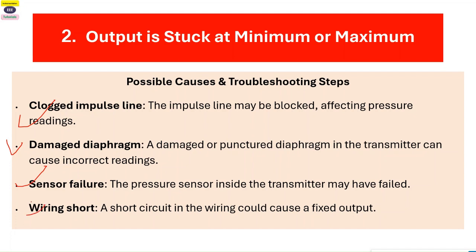So you have to check whether your transmitter wiring, your junction box wiring, and the final wiring are not short or not open. Otherwise your signal may be stuck at minimum or maximum. So these are the possible causes.